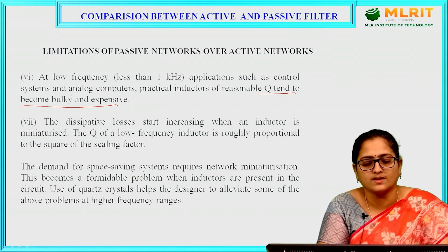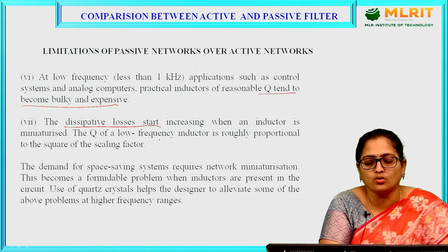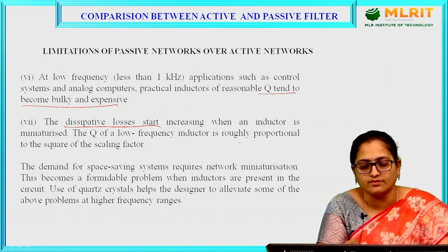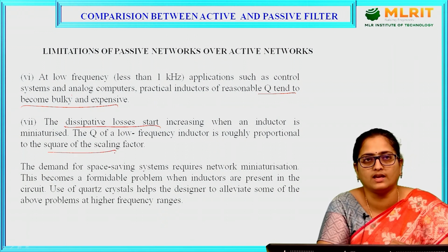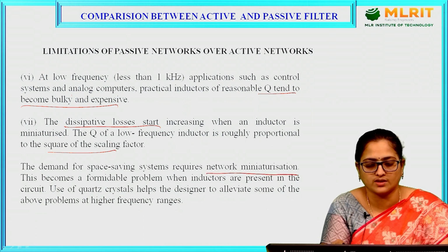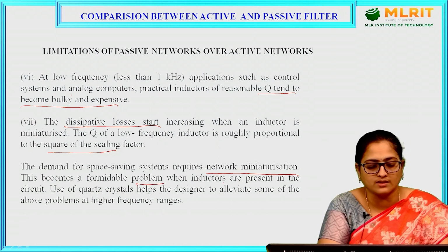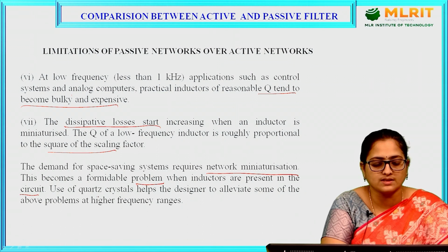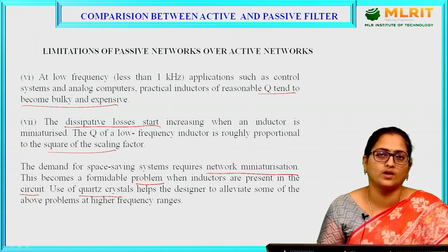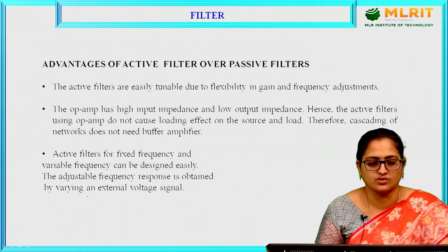The dissipative loss starts increasing when an inductor is miniaturized. If you want to reduce the size of an inductor, the dissipative losses start increasing. The Q of a low frequency inductor is roughly proportional to the square of the scaling factor. So the demand for space saving systems requires network miniaturization. This becomes a formidable problem when inductors are present in the circuit. The quartz crystal helps the designer to substitute for inductance in the high frequency range.